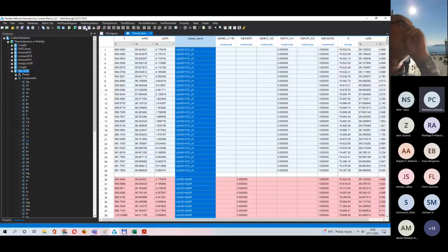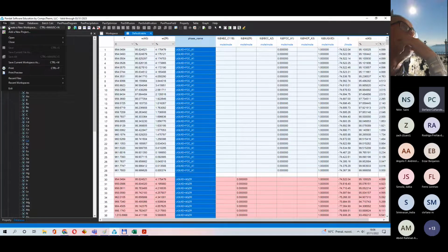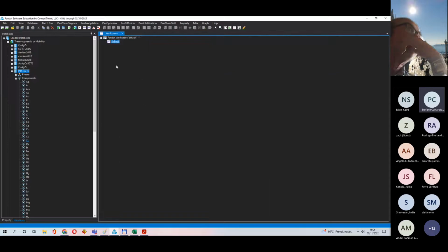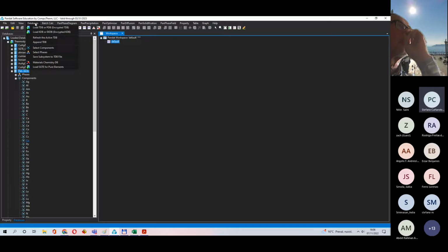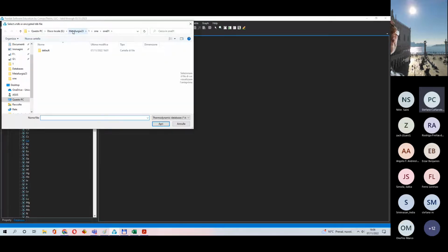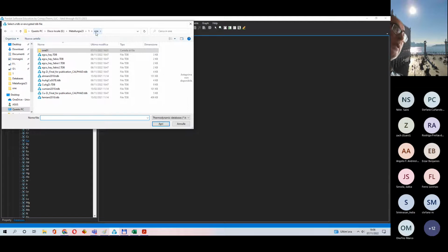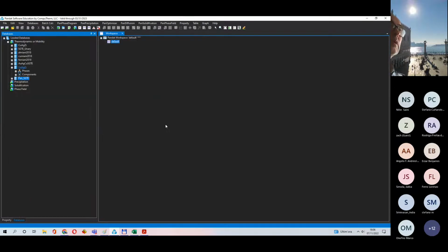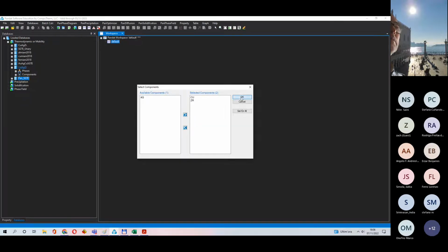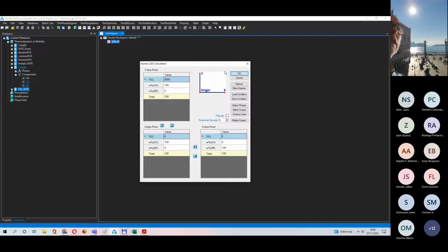And well, you have seen that we have different menus. Let us again create a new workspace and do something relatively simple. So database, again, we will produce a binary phase diagram using, for instance, copper zirconium. Load a thermodynamic database. It is the zipped or unzipped file that you have, with copper, silver, and zirconium. Select components: we will select only copper and zirconium.